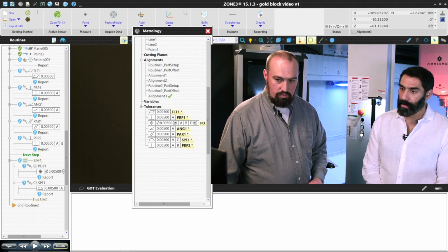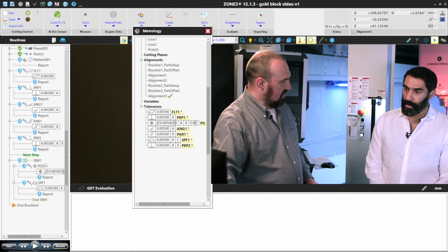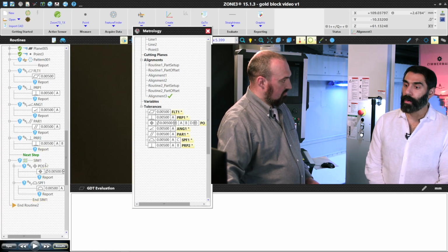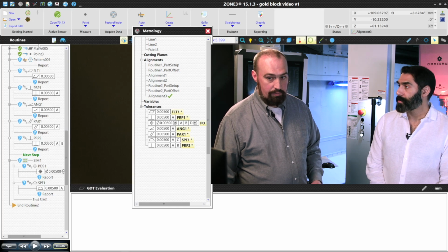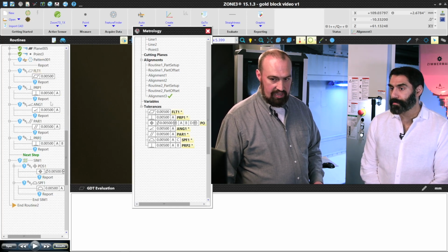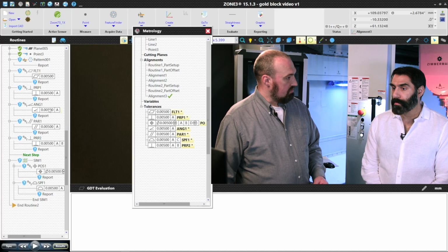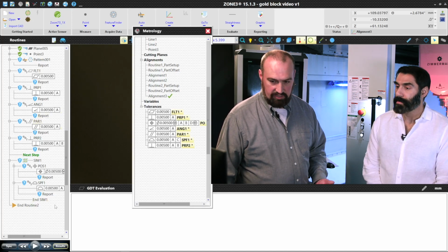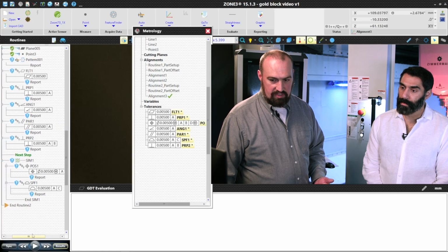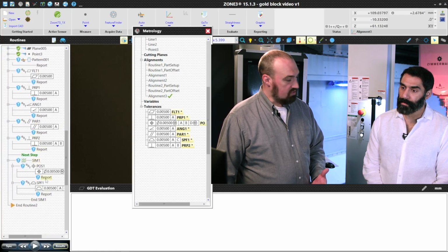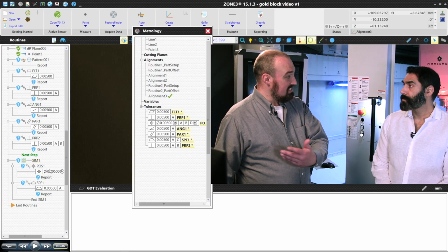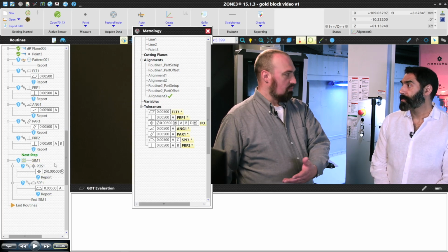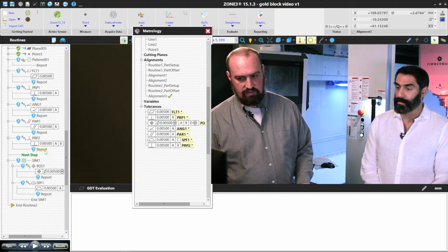It also brings things in simultaneous groups where it's applicable. Things that are operating with different datum reference frames are not necessarily subject to that. But if we have something where, according to the standard, it applies, it'll bring that in as part of a simultaneous evaluation.